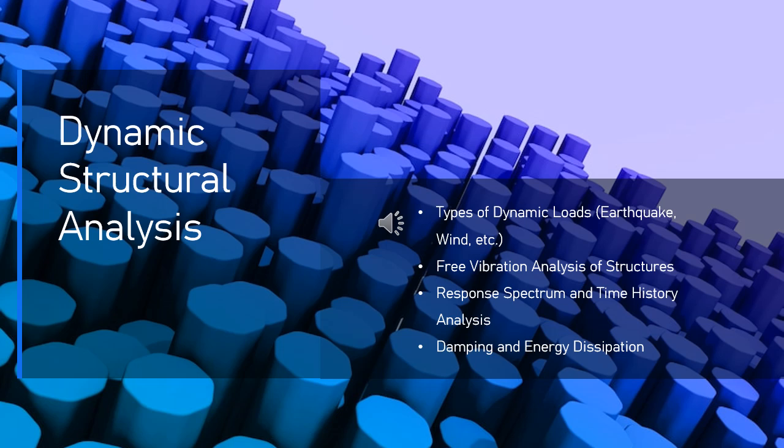For structures with joints, connections, or sliding parts, energy dissipation can occur through frictional resistance. This type of damping is nonlinear and depends on the displacement and velocity of the sliding surfaces. 3. Viscous damping. Fluid-based systems. Damping can also occur in systems where a fluid, like oil or gas, is involved, such as in dampers used in structural systems, e.g., shock absorbers. Energy is dissipated as the fluid resists the movement of a piston or other components.